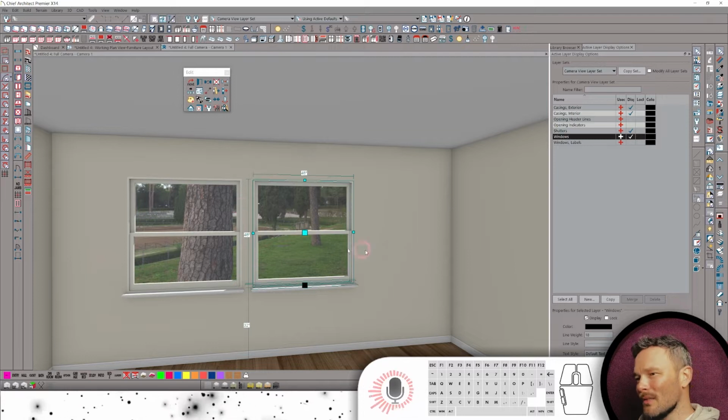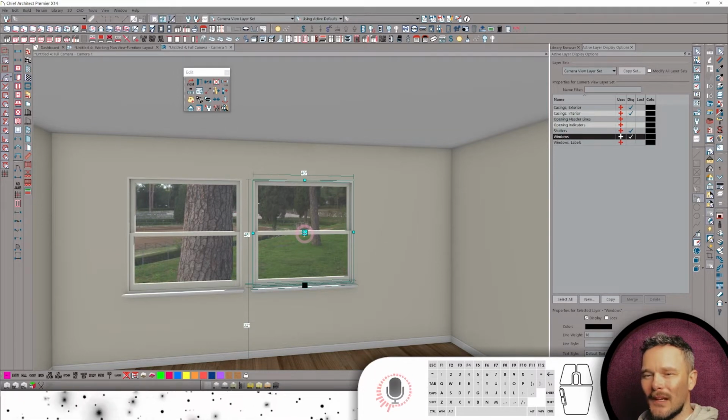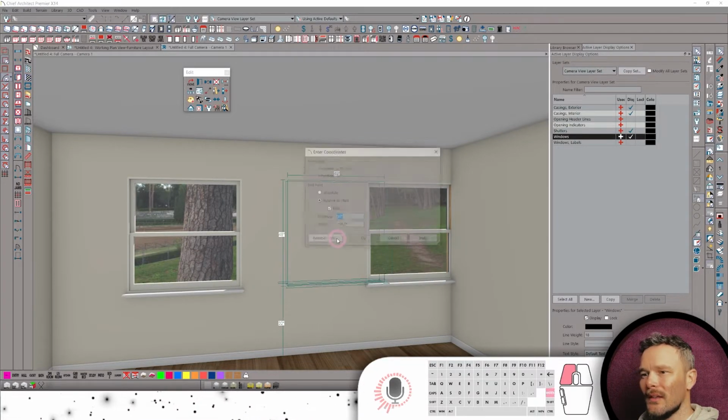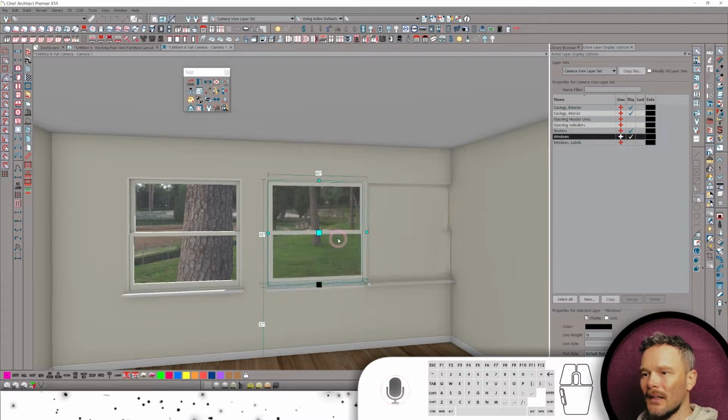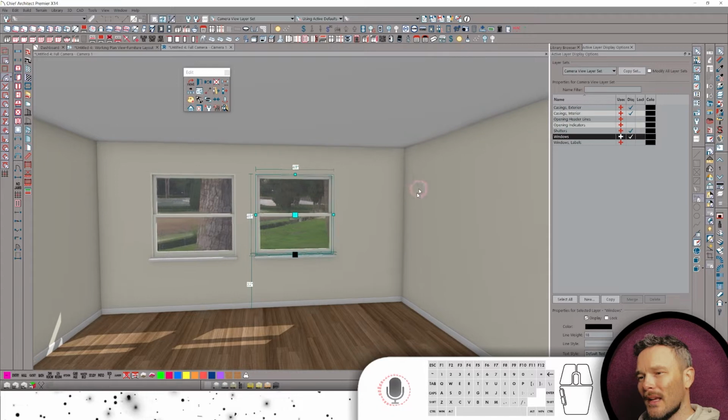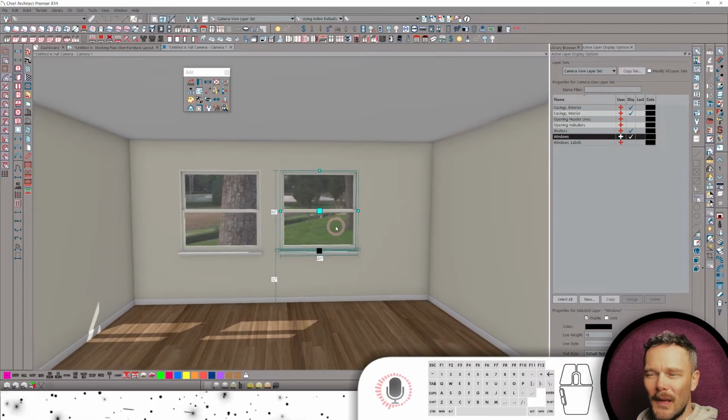When I'm measuring in the field in as-built or existing conditions, I like to be able to measure in 3D, throw my window all the way to the corner, and then do an offset back from there. Because of that, I do not have casings. When you have casings, it will butt to that casing, and that's problematic for me.